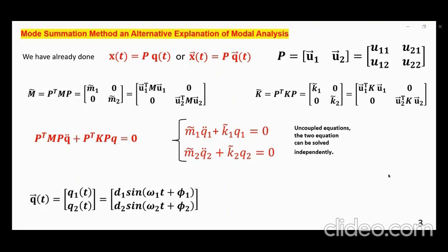Now, we spent about 8 weeks on these single degree of freedom systems, and we found out that if you have an equation like that, you can actually solve it. The solution is going to be just an amplitude times sine of a frequency, which goes with this equation, which is frequency 1, and then there is a phase angle.